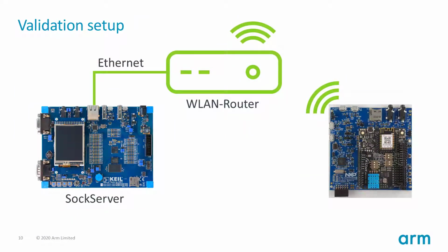Before I verify my application software, I run the validation suite on my setup to make sure that I have used the right hardware and software and can connect to Wi-Fi. Otherwise, I might encounter problems later that have nothing to do with the actual application, but simple configuration errors. Setting up complex SoCs, such as the LPC55S69, requires additional tools and can quickly lead to a non-working project. The validation suite verifies the API interface interaction using the driver capabilities, as well as valid and invalid parameters. It initiates data communication with various transfer sizes and parameters, such as the baud rate.